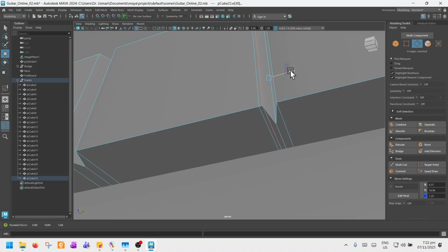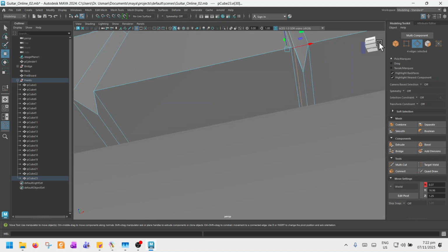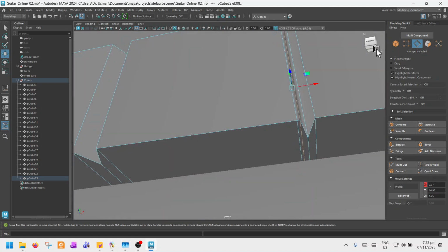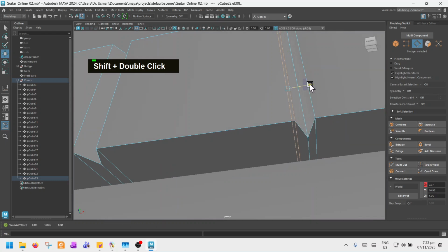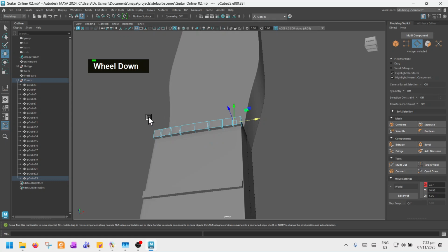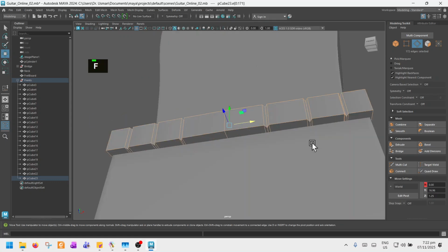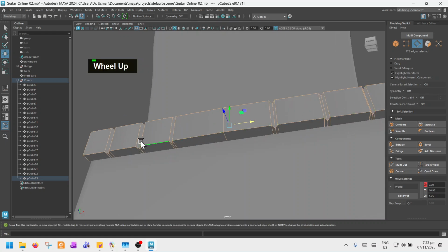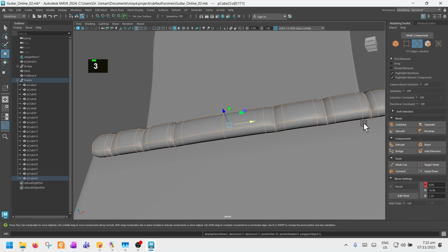make it a little larger like this. Okay, so then we will shift like this one and move away like this, and this one a little bit like so. It is better now. So I'll select these and press F to take any focus. Now we need to increase the number of edge loops around them to make them sharper, because if you press 3, you see it becomes very softer. So we need to make the edges more sharper.